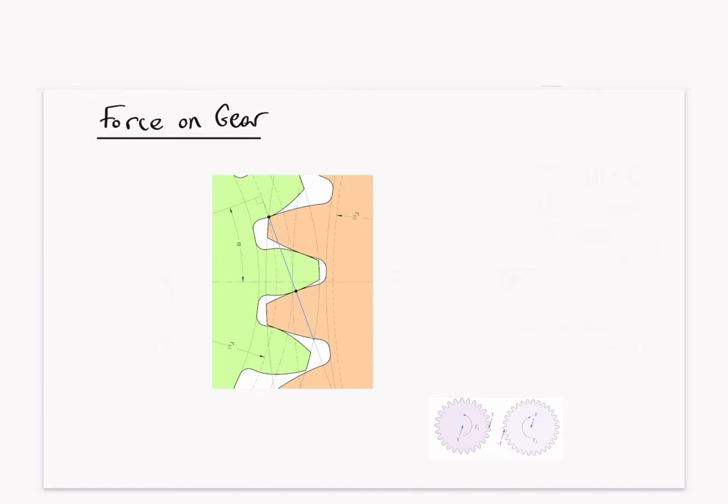And this line here is called the line of action, because that's the line at which our force is occurring on our device. Right now, at this point right here, it's going to transfer as the device moves around. But we can see that there's a reactionary force operating at this point, and that it's operating at our pressure angle of alpha.